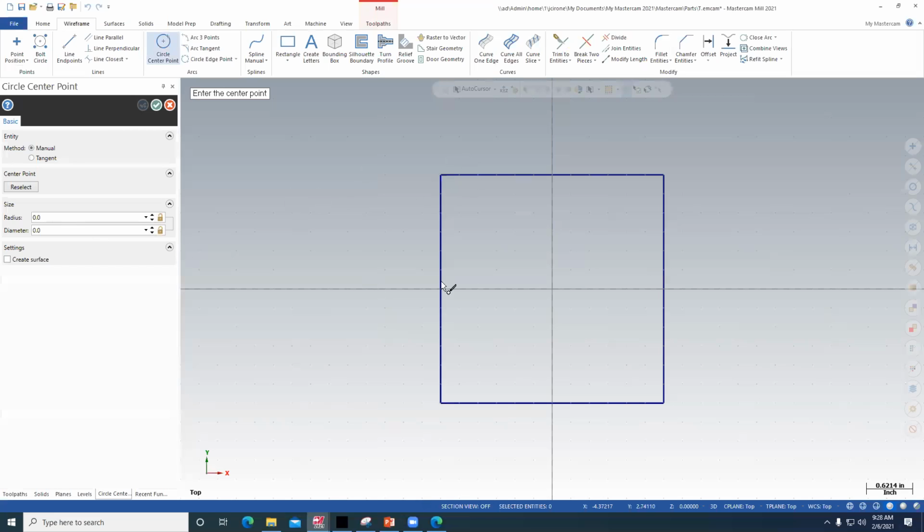When you draw this, maybe you do a center rectangle. I go rectangle here, and all the options are listed right here. So I go center rectangle, and I say make this 3 by 3. It's really easy work. Just go over here, here's the auto cursor, set. Snap the origin, and I can green check mark and get this out.